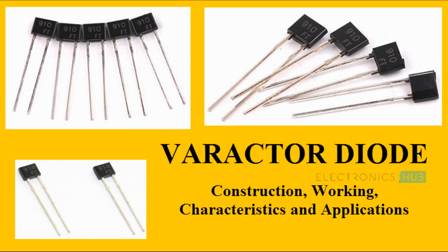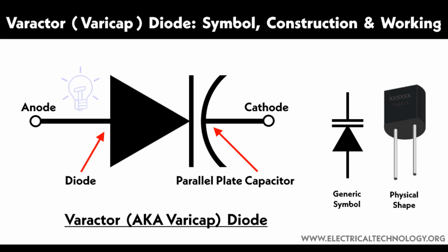In a voltage-controlled capacitance device, such as a Varactor diode, the capacitance between two conductive elements, such as metal plates or semiconductor layers, changes in response to changes in the applied voltage. This effect is typically achieved by exploiting the variation of the depletion region's width in a p-n junction diode or a similar structure when a voltage is applied.